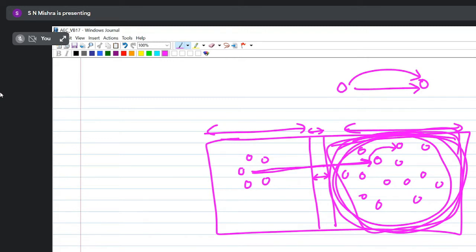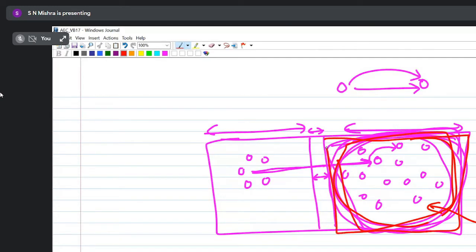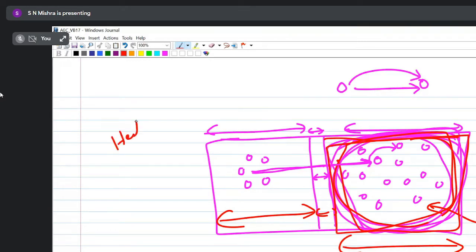So that's why two things are done here. One thing is doping is less to minimize the concentration here. Another thing is the width is also wider. If you compare the emitter, base and collector, the collector width is more, so heat per unit area will decrease. So the power dissipation capacity will be a little bit stabilized. Okay, so two things are done here.